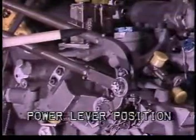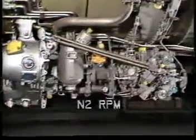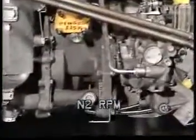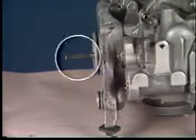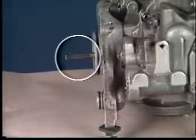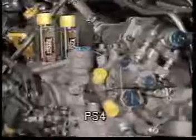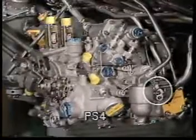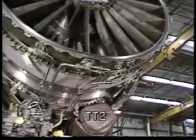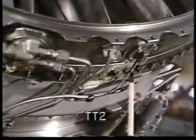power lever position. This input is the pilot's request for thrust. N2 RPM, a mechanical input which is provided by the rotation of this shaft and is proportional to high-pressure compressor speed. PS4. This input represents the amount of air available for combustion. TT2. This temperature input biases the fuel flow schedule during engine idle and rapid accelerations.